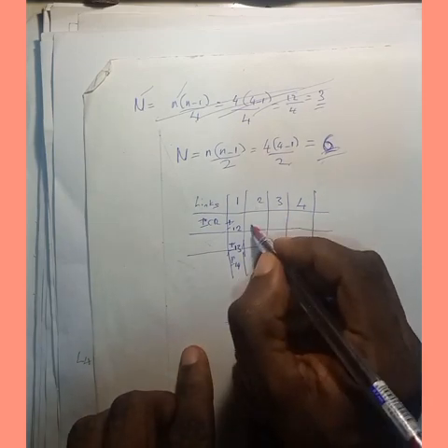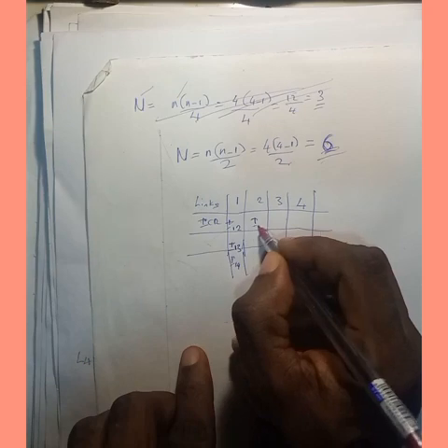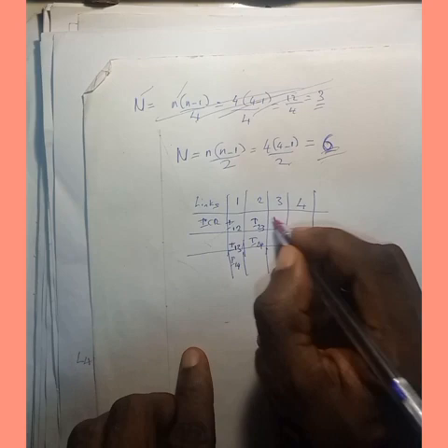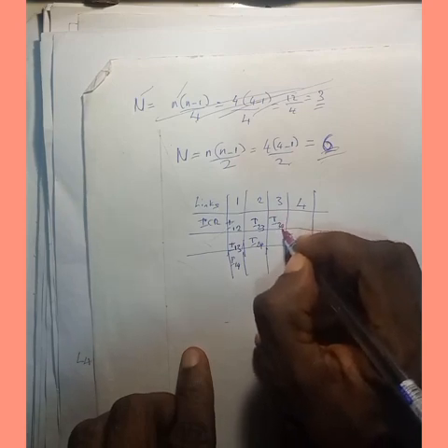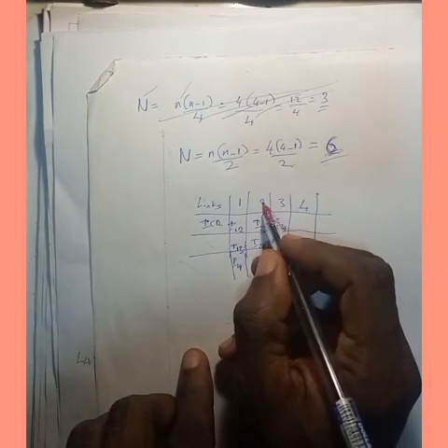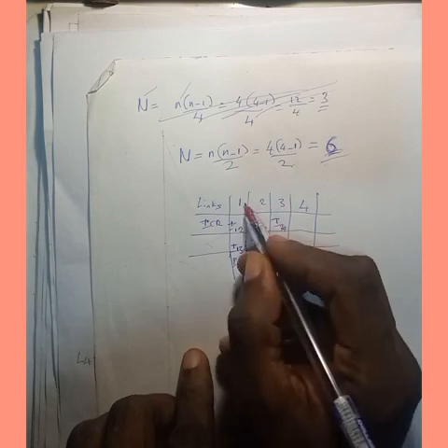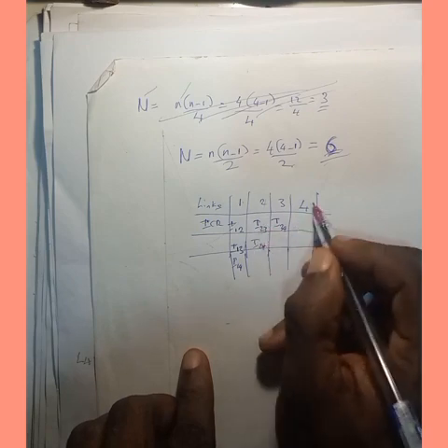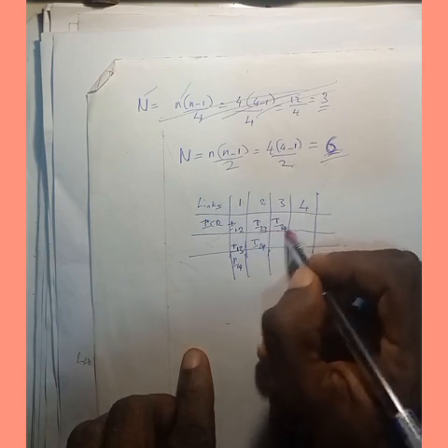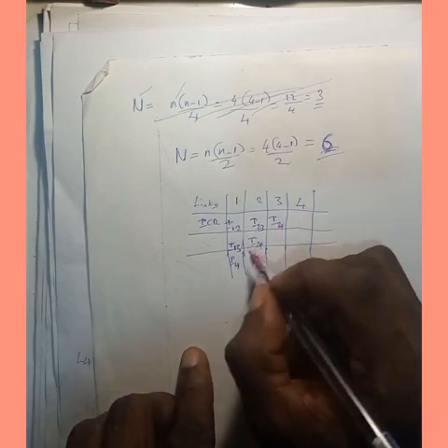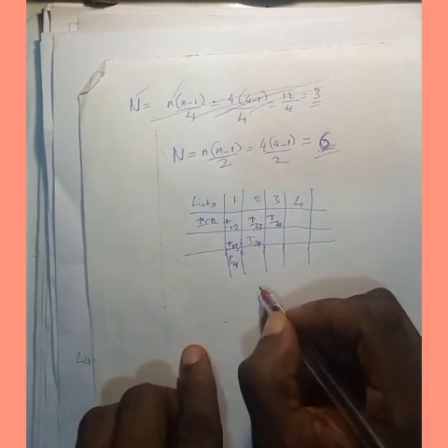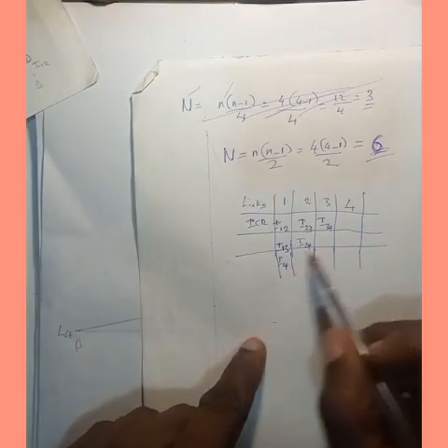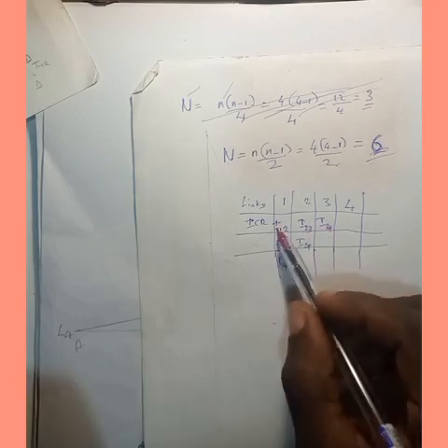The same thing, you come down here, this is I23, I24, and then here you have I34. So here you have 1 reacting with 2, 1 with 3, and then 1 with 4. Here you have 2 with 3, 2 with 4, and then I3 with 4. But you cannot have 4 with 1. It has to be the smaller number before the larger number. So from this table, it means the total number of instantaneous centers we have are just 6: 1, 2, 3, 4, 5, and then 6.